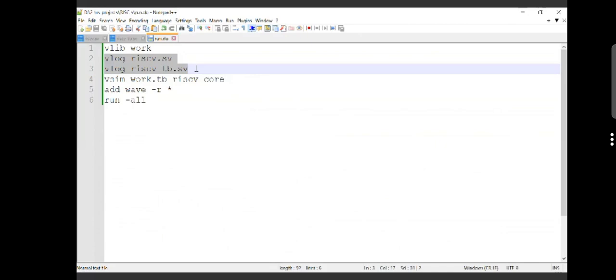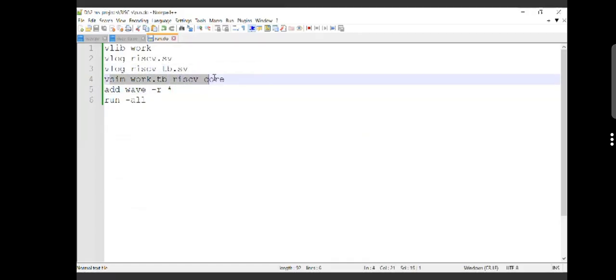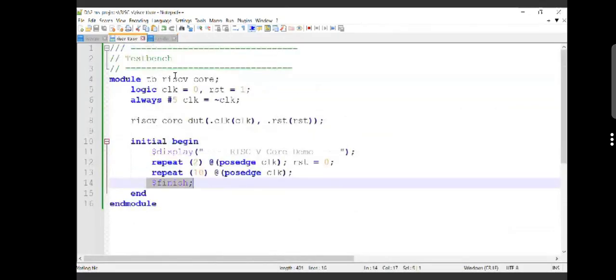So first I need to compile to check whether these both files are proper or not. Like syntactical issues, or am I missing any semicolons, or if I have declared the inputs but did not connect them at any place. Syntactically from top to bottom it will check that, and it will tell whether the code is 100 percent, meaning compiled successfully or not. Okay, and coming to the simulation, I need to run the simulation, where we are giving the module name of our simulation. So my module name of my simulation is this module name I'm giving here.